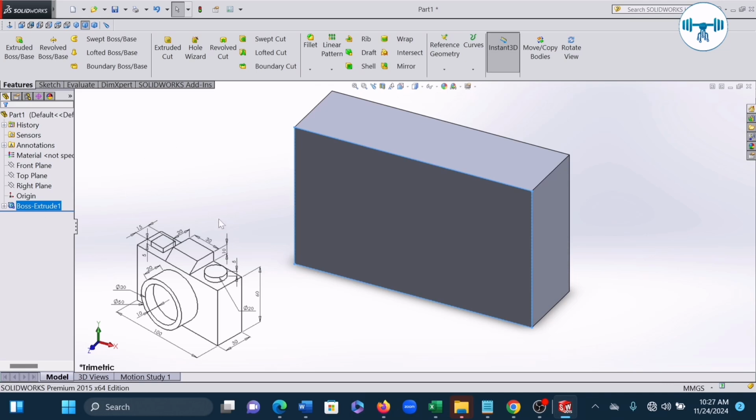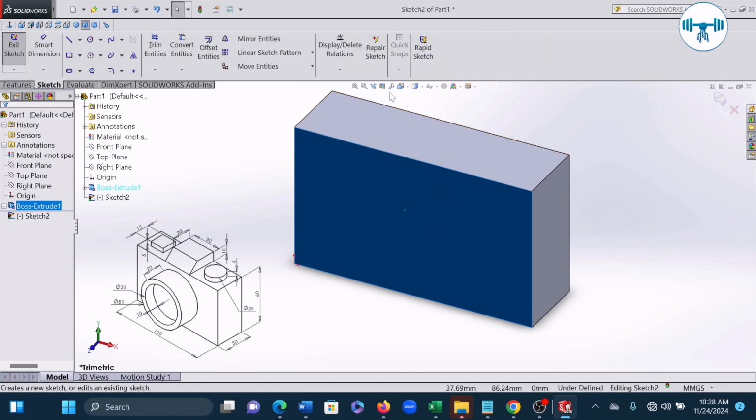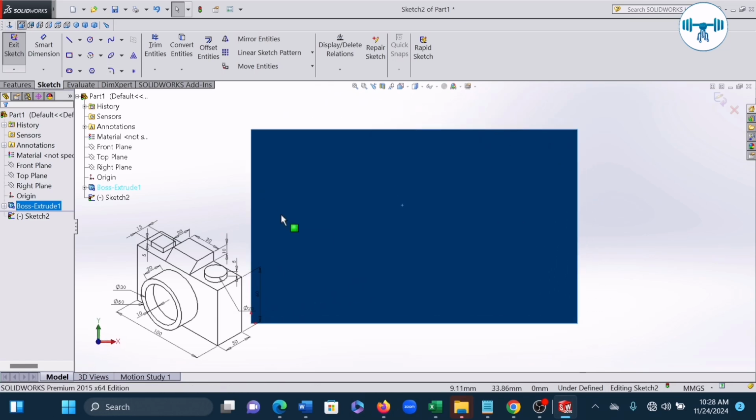So now I want to start a new sketch. So what am I going to do? I will come to this face where I want to put the next sketch. So I'm going to click on this face and then open a sketch on it. Can you see sketch? I'll open a sketch on it. Then remember, I brought my view tools out. I'm going to normal to plane. So normal to plane positions it normal to my screen.